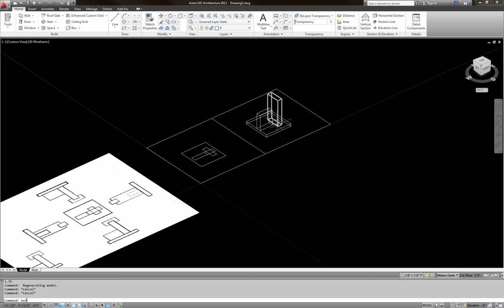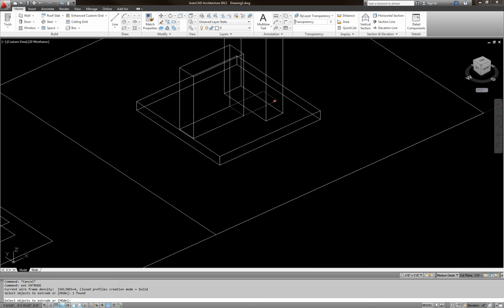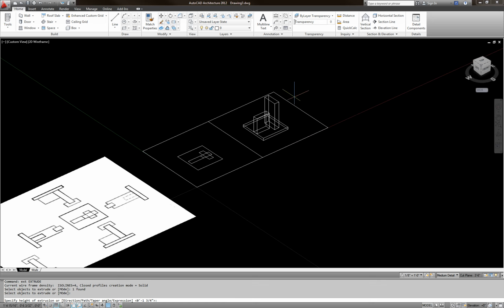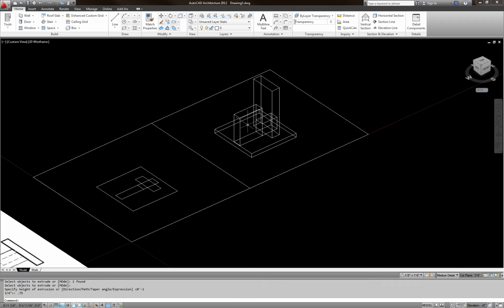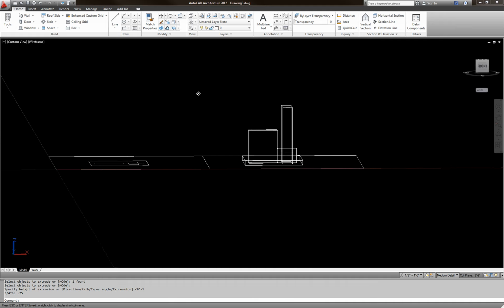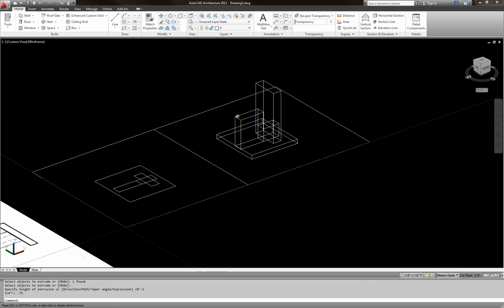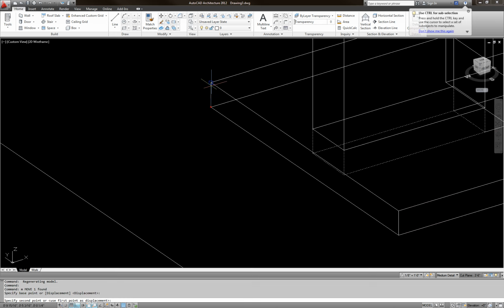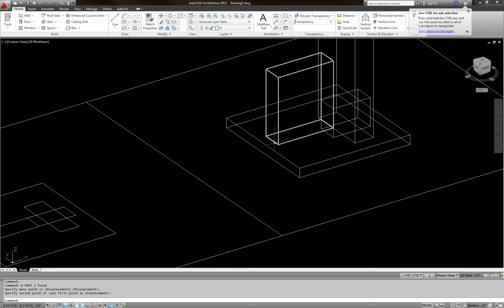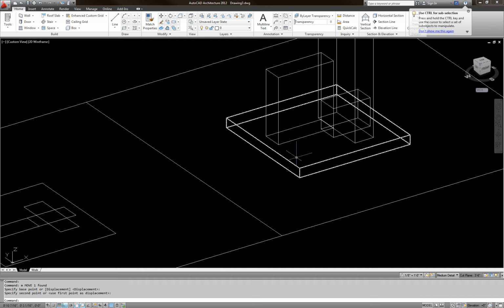Again, ext extrude, click on the object. Okay, enter. See, now you can either go down or go up. Okay, so I'm going to go up. I'm going to say 0.75. Now everything, if you look here, everything is the base. Okay, so the way I'm going to move everything up is by clicking on this, enter. I'm going to go to this corner. Now I'm going this corner. So now this object is on top of this.